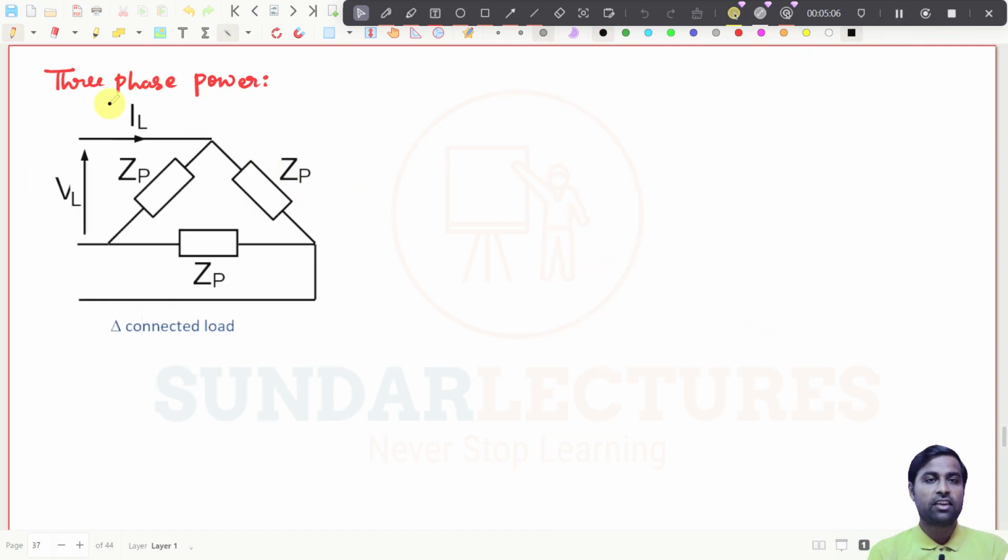Next, three phase power in a delta connected system. This is very simple. Again, this is the line voltage and this is the phase voltage. Both are the same here. We know that in delta connection, VL is equal to V phase, and IL is equal to root 3 times I phase.